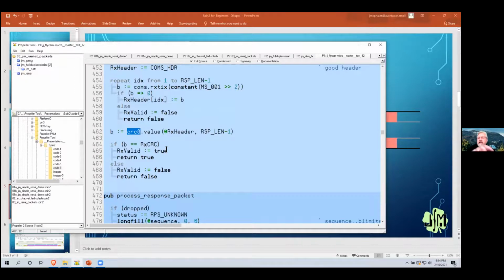So I had a CRC8 calculation in Spin that has been around forever. It's the same one that comes from the one-wire code, and the version that I use was written by Micah Dowdy. It works really nicely and it's clean and easy. And it's one of those things where it was a trap because it was a cute little tiny bit of code that looked innocuous, but if you think about it with CRC, you end up having to go byte by byte, bit by bit. And in the receive packet, it's a few bytes, and it was taking an enormously long time to do the CRC relative to the size of my packet window, and that was breaking it.